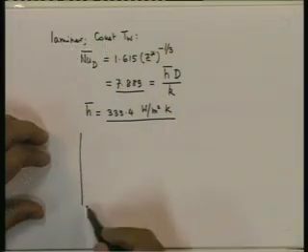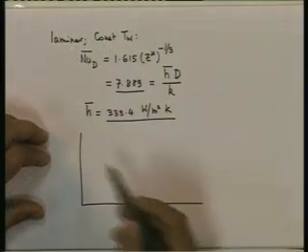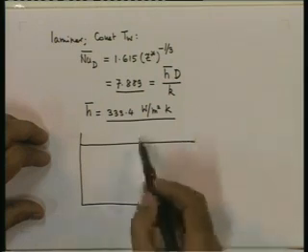So we should be able to determine the heat flow rate from the wall to the fluid, because heat flow rate from the wall to the fluid would be heat transfer coefficient into area into temperature difference between the wall and fluid. However, because it is a constant wall temperature situation, we have a uniform wall temperature.